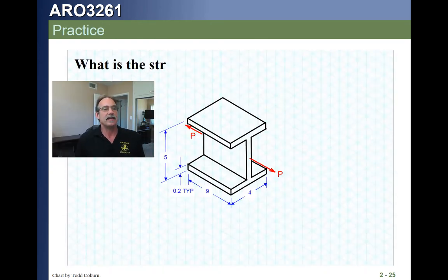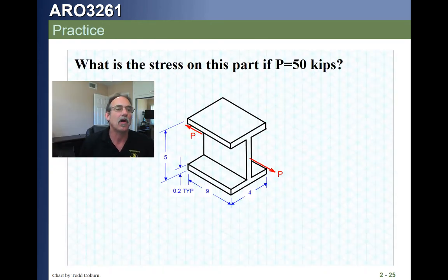What's the stress on the part if your force is 50 kips? Well, what you do is you calculate the area of this part. How many guys can calculate the area of a section? You should not have made it through statics without being able to do that, because we learned that in statics. Calculate the normal area, divide the force by the area, that's your stress. Got it?